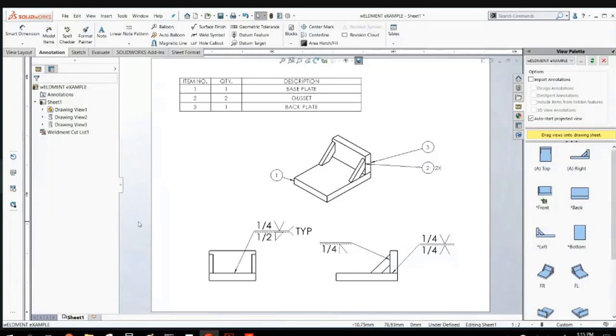So that is really the quick 15-minute tour of the basic weldments. It's a multi-body design. SolidWorks will automatically do geometry checks to give you a quantity count on those multiple bodies. When it has similar bodies, it just gives you a quantity count of 2. And then that can be accessed just like a bill of materials.